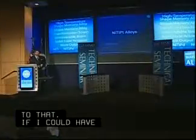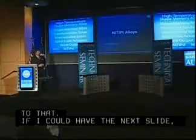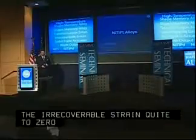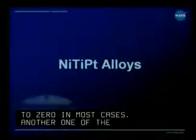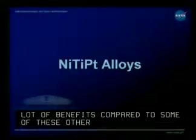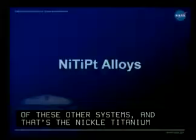We've done a lot of work on the palladium alloys. Unfortunately, we haven't gotten the irrecoverable strains quite to zero in most cases. Another one of the systems that we've been working on offers a lot of benefits compared to some of these other systems, and that's the nickel titanium platinum system. And it's unique for a number of reasons. If I can have the next slide.